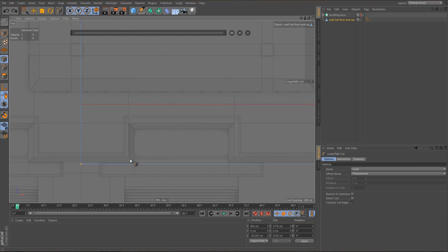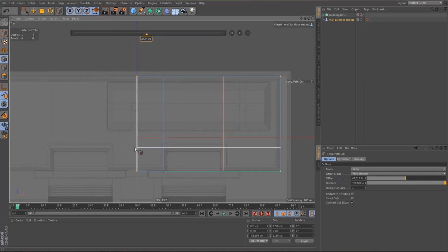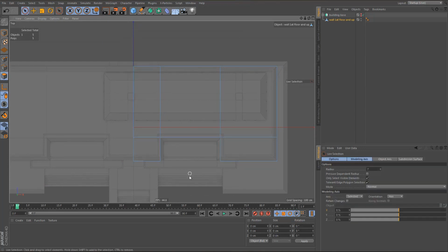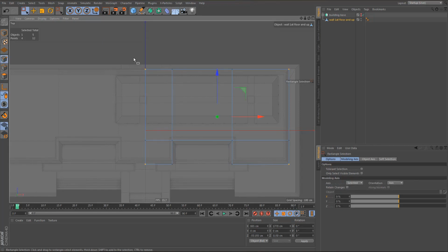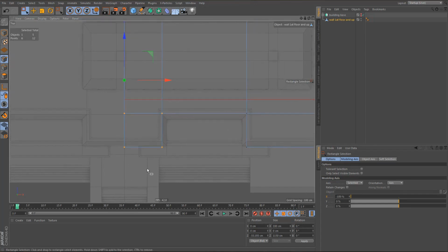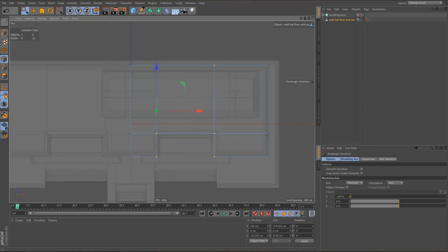And I think we need to make these on these lines here, and we also need a cut here, and then we can delete this polygon, and I'll adjust the dimensions a little bit. I'll make this 330, and I'll make this 750, and this is 690, so let's do maybe 725. I want these to be about the same width, 715, 725, I think that's fine.